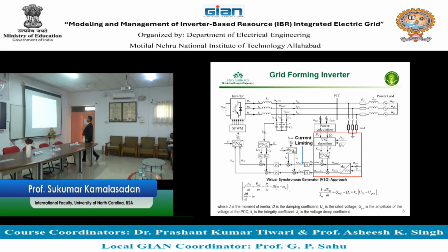So two equations you can add. Then it will become third order, right? The third order swing equation, the emulation of the swing equation. So you can actually use this algorithm and change the algorithm E and theta based on J, which is called inertia. Now that J becomes inertia emulation. You are emulating inertia much like a synchronous generator.